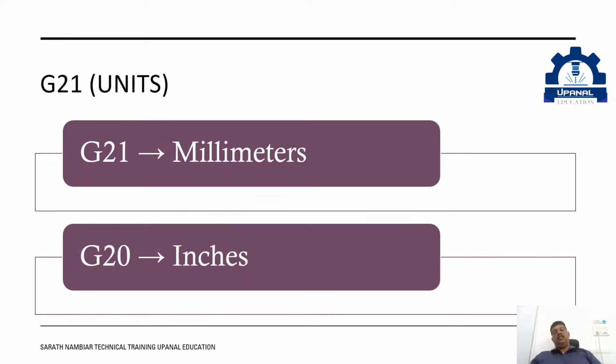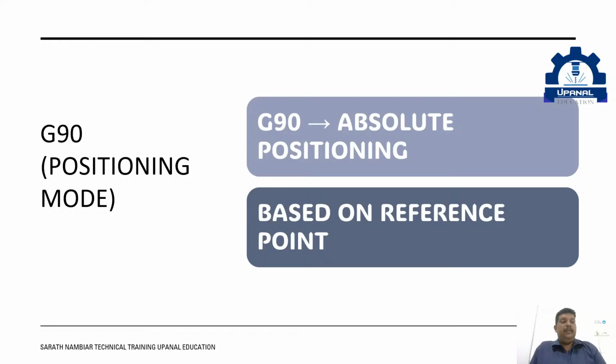Let's understand one code from that line. So G21, this tells the machine that we are going to use millimeter as a unit. So imagine this situation, for example. You think your dimension is 50 mm, but the machine moves to a position X50 from the 0 point, not from the current position. This is very important for accuracy and repeatability. There is also another mode called incremental. But for now, just remember this idea, G90 is a fixed reference system and this helps maintain consistency in the machine.